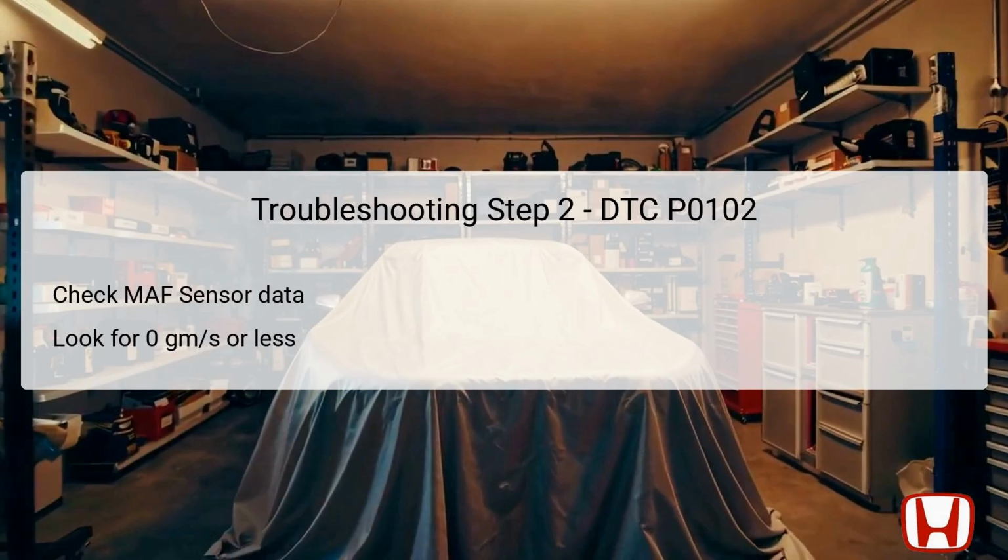In such cases, a visual inspection for poor connections or loose terminals at the MAF and IAT sensors, as well as the ECM/PCM, is warranted. This step requires you to turn the ignition switch to the LOCK (0) position. Effectively, this action powers down the system, allowing for safe disconnection of components without risking any electrical shorts or other complications during subsequent diagnostics. Preparing to check the fuse is a crucial next step, ensuring that the electrical circuit to the MAF sensor is functional. This precaution helps to establish whether the issue may stem from other components in the electrical system.